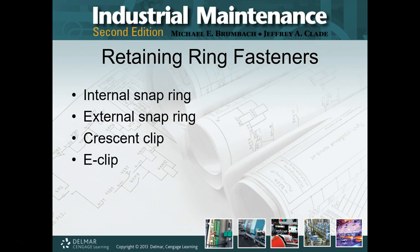Fortunately enough, retaining rings typically don't run into that problem. So we've got internal, external snap rings, as you saw on the page for it. I did them as one. They kind of look the same, but not really. The internal snap rings are perfectly round on the outside, and then you've got the little dip, the two nipples, dimples, whatever, so you can get the snap ring pliers in to remove that snap ring.